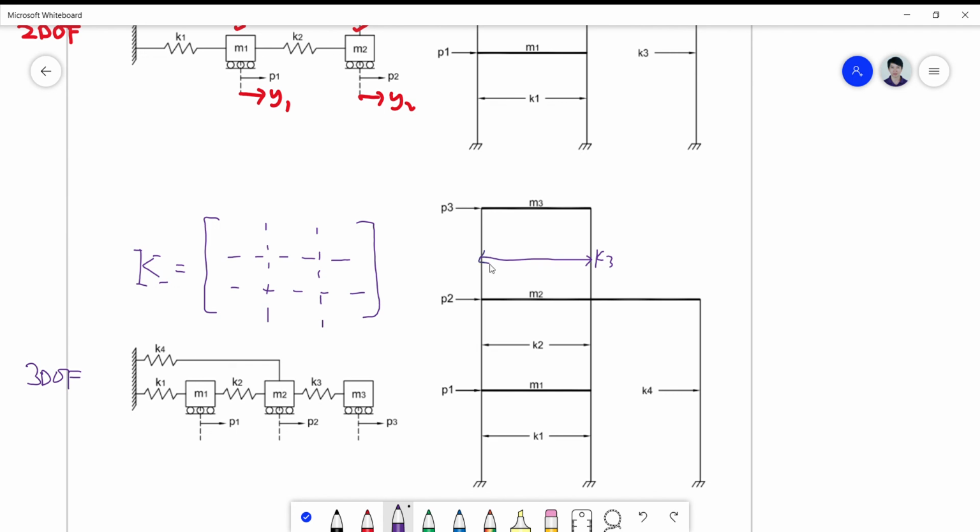Okay, so how do you now apply the connectivity? Again, you write the coordinate system involved. You have a 3DOF, and then take a look into the model itself for connections. Okay, a K1 1 simply is a K1 plus K2 there, and a K1 2 is 1 and 2 is connected with a negative K2 there.